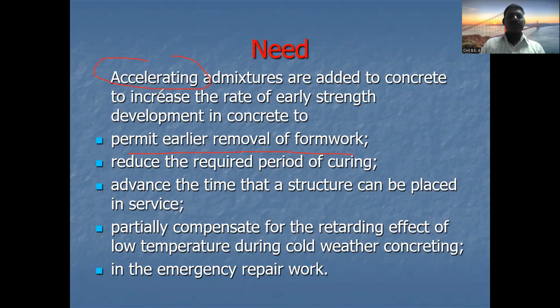Why? Because we are using accelerating admixtures to get the early strength. To get the early strength, we are using accelerating admixture. If we get the strength of the concrete in early days, then we can also remove the formwork early, it means not as per the specified days.